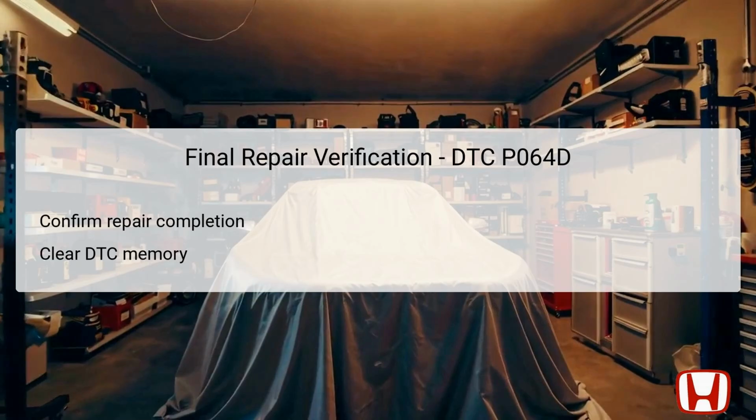This action ensures that the vehicle can undergo a fresh diagnostic evaluation without the interference of old fault codes. Lastly, it is essential to test drive the vehicle to monitor for any reappearance of the DTC and ensure that engine performance has returned to normal. This thorough confirmation process is crucial for the long-term reliability of the repair.